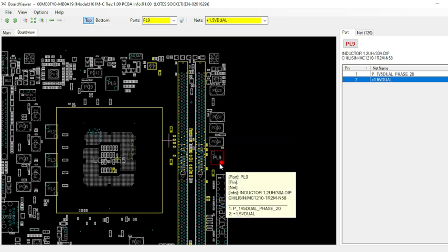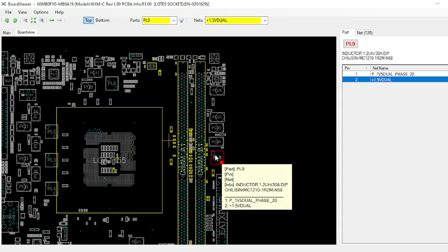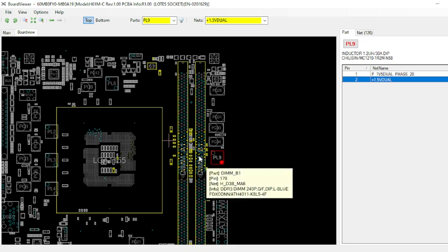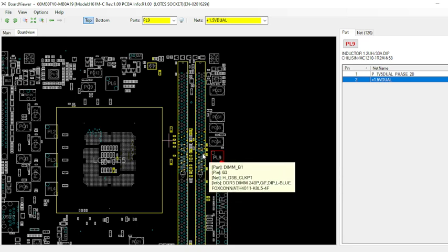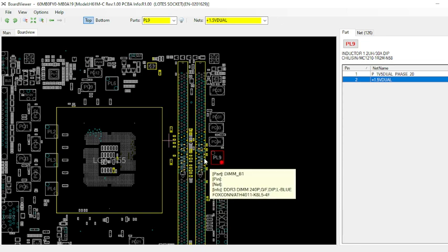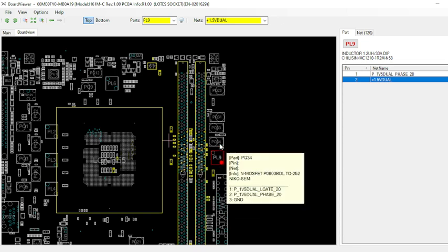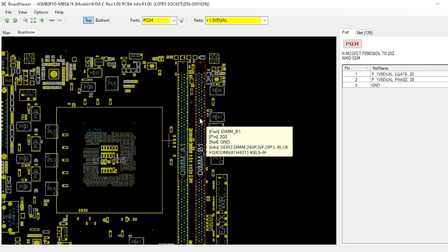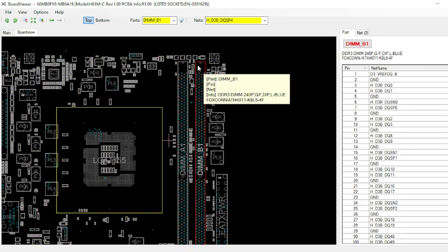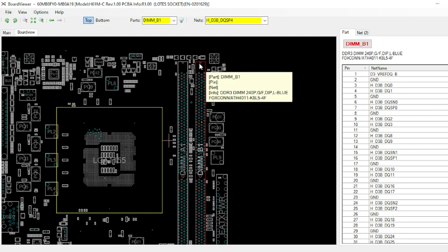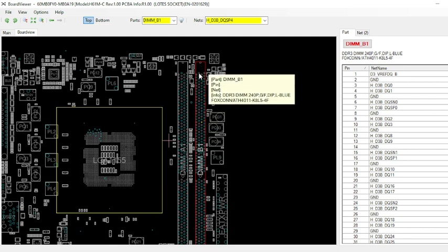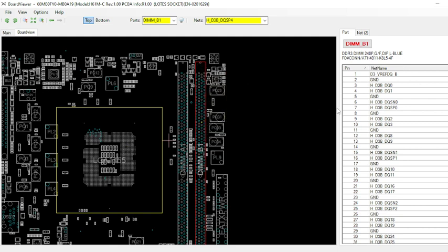Again, you can check this RAM supply. Whenever RAM is connected, you will find some SMD capacitors on the RAM, and you can check the RAM supply on those SMD capacitors also. This is the main supply which you have to look at. After that, we have to check some other supplies. So let me select this RAM. First we have checked our RAM supply.